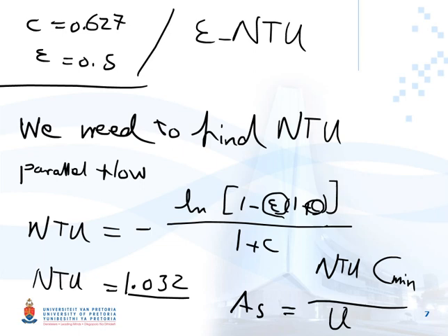They say that you can use that correlation when the Reynolds number is between these two values, or when the Prandtl number is between those two. So when you find the right correlation for Nusselt, you find the Nusselt number, and after that the heat transfer coefficient can be calculated easily when you have the Nusselt number and k, which is thermal conductivity.